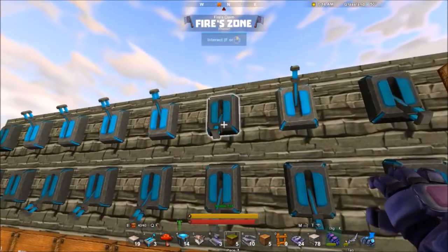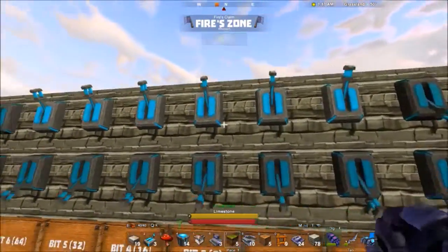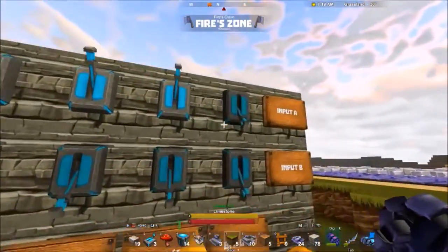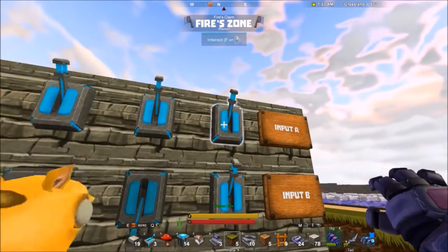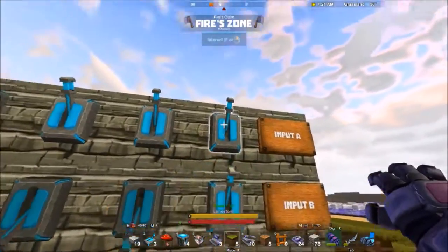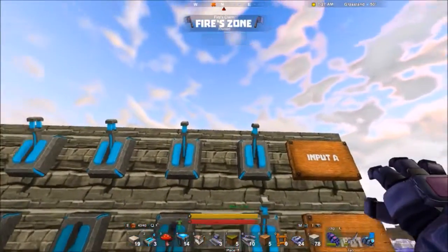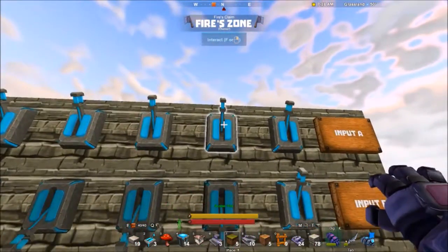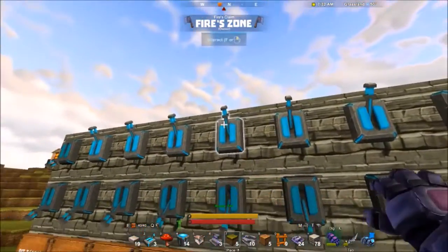So having a 1 means that it will propagate it. Let's say right now all of these ones are propagating the carry. If we generate the carry right here, the carry is generated with an AND, meaning that you have two 1s. Then it will come here, this will be 0, and it will pass a carry as 1.